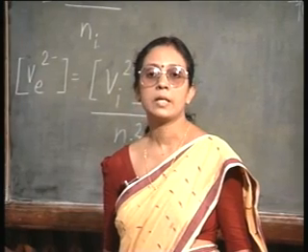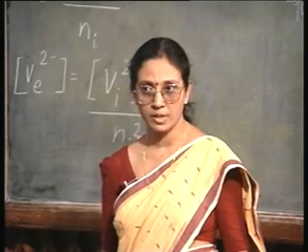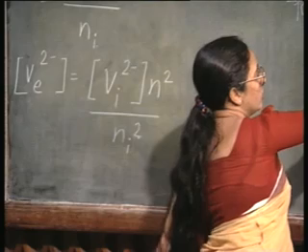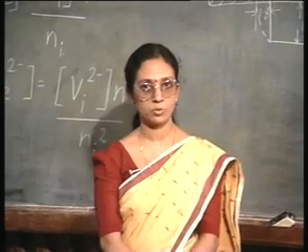So, you should take care of this in your device design, otherwise you have two diffused regions, you are thinking that they are separated, but they might get shorted if you do not take into account this lateral diffusion situation.